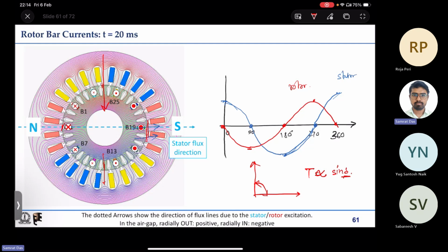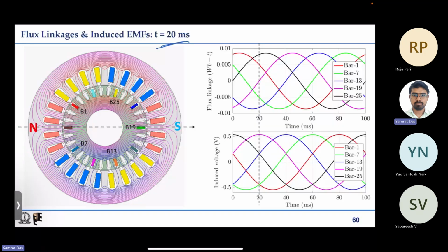But unlike this, in the synchronous machine we won't have this delta angle to be more than 20 30 degree, because otherwise it may go out of synchronism, and there may be instability because of that. So in the synchronous machine we have to stick to very low delta values, but in the induction machine, if it rotates at very close speeds to synchronous speed, then we can have 90 degree, which is ideal for torque production.